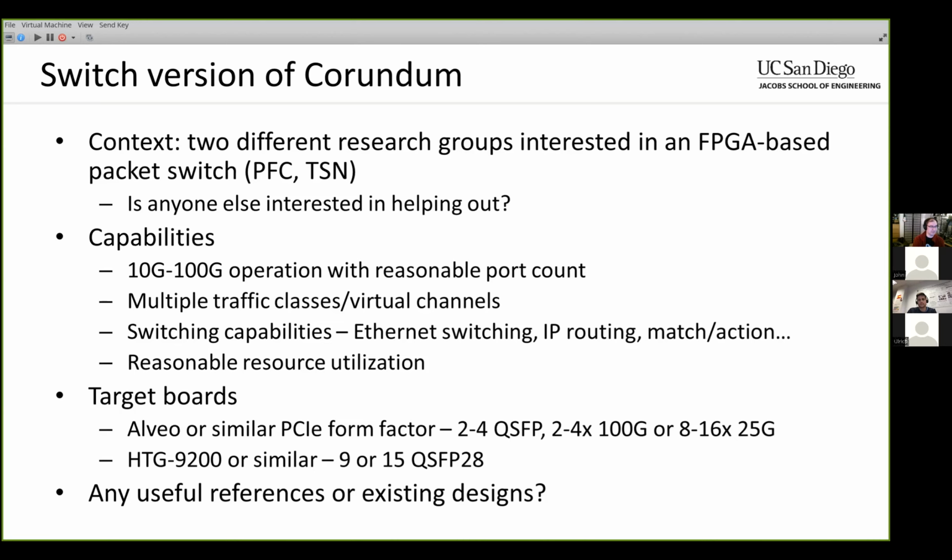But there are other boards available. I know High-Tech Global make 2 things. They make a big honking FPGA board with a bunch of QSFPs on it. They also make an FMC Plus adapter, which has 6 QSFPs on it. So you can get something like a VC118, and you can whack one of these 6 QSFP adapters on there. You can get 8 QSFPs on one board.